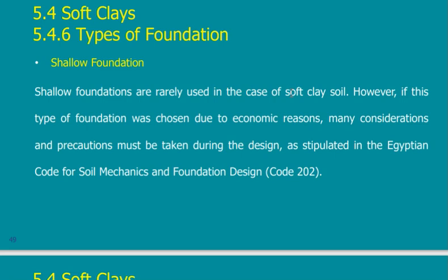Use tie beams, ground beams, but use them very big, very stiff, so that in case I have some differential settlement between footings, then these ground beams would help in acting, the whole of my foundation would act like a grid. It's one grid connected with perpendicular beams in all directions.